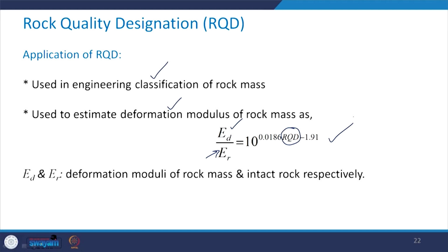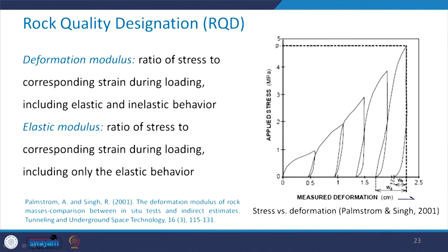Now, till now we have learnt about the elastic modulus. What is this deformation modulus? I will be using this pretty often throughout this course, so right at this point it is important for you to understand this term. Take a look. Here on the x axis you have the measured deformation, and here you have the applied stress. The difference between deformation modulus and elastic modulus has been given here.